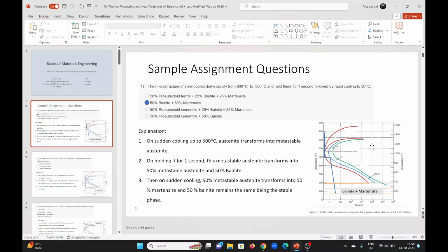So if you are trying to heat your material or cool your material, if it is an insulator, then there will be a large gradient in temperature between both sides. That's why you use foams or various insulator clothing to help yourself in winter, or you use refractory, which is also an insulator, to prevent heating of your room compared to your furnace. So the temperature gradient will depend on your thermal conductivity.